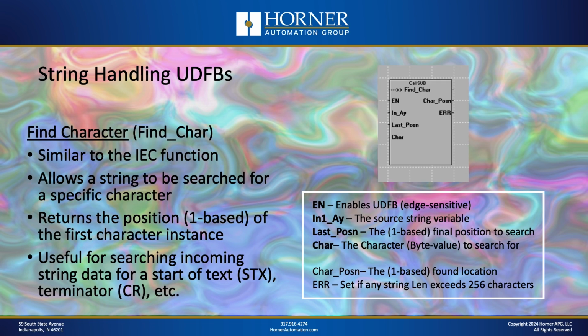Here's find character. Find character is very similar to the find byte function we've talked about earlier, but with find character, you can find a specific character in a string. Where is the carriage return in this string that I just grabbed by scanning a barcode? Because maybe that carriage return signals the start of a specific data field, or maybe it signals the end of the string, which can be a variable length. So for all of those sorts of things, find character can be really useful.